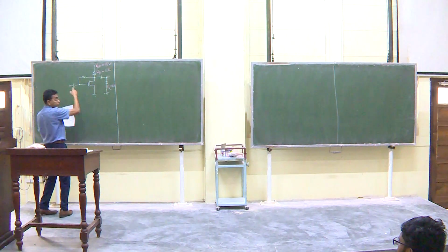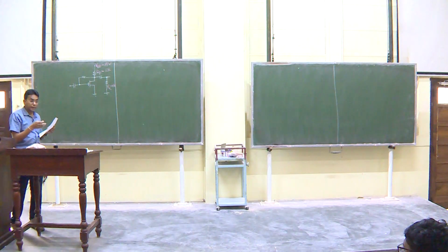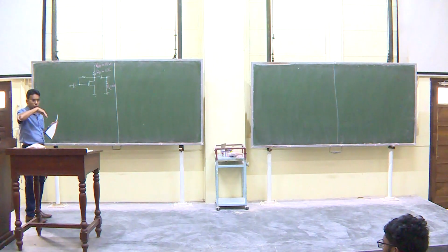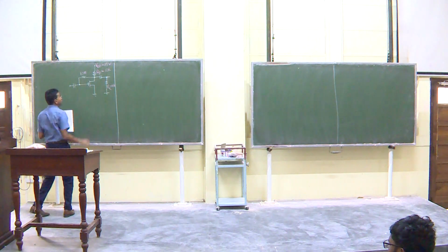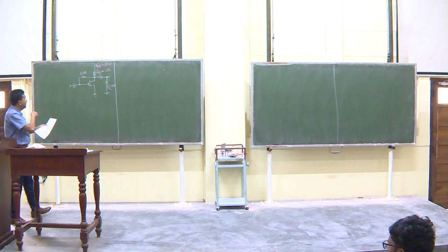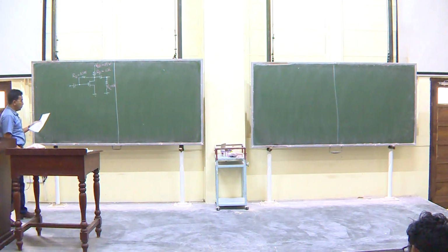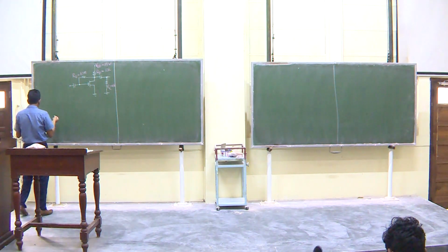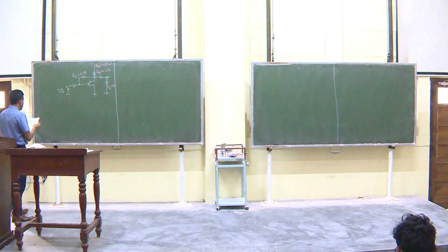This is the biasing resistor. Remember, all you need is a voltage. You don't need to provide a big current, because of the oxide layer in the MOSFET, no current flows, right? So all we put is a very big resistor, 10 megaohms. This is RG, 10 megaohms. And the input voltage is provided here.